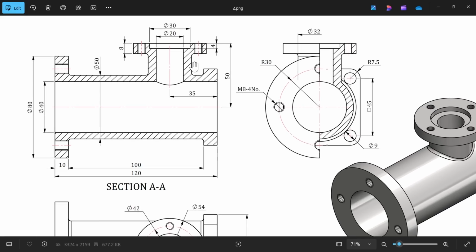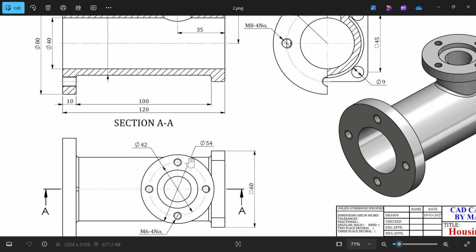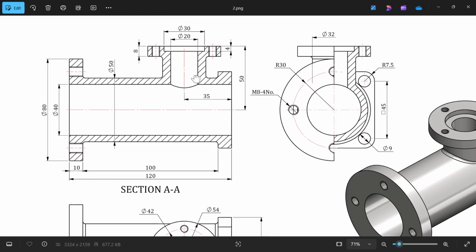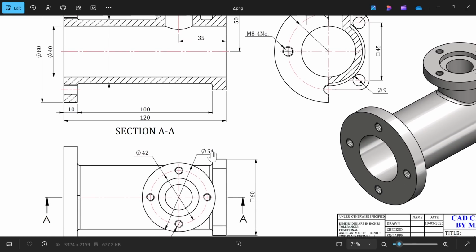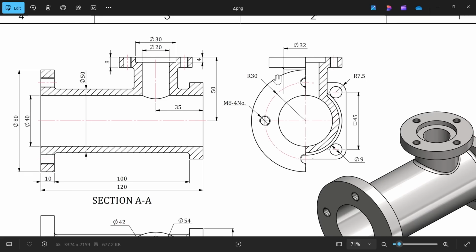Now let's add this pipe from upside, 35, 50 millimeter from here to here. Now check this upper radius diameter, how much. You will observe here 54. Then there is a hole, this hole depth 20, then one counter bore hole, depth 4 millimeter but diameter 30. Okay, so 1, 2 and the outer one 54, and the thickness you will see 8 millimeter, 50 millimeter from here. And this internal one you will observe here, see, 32 millimeter.